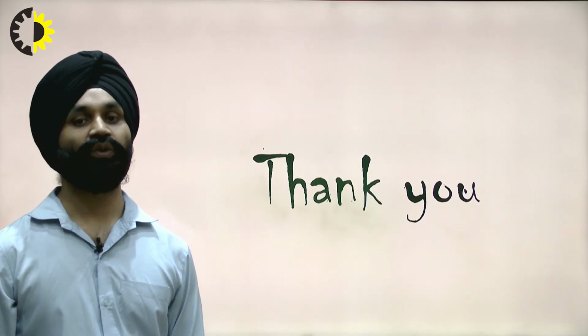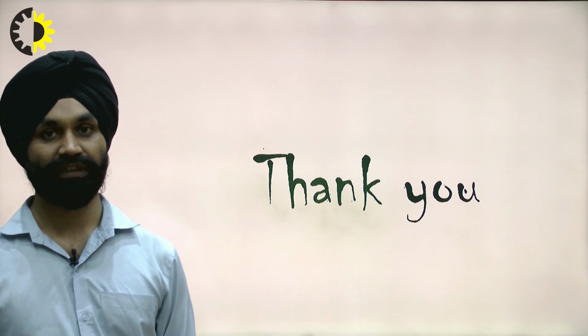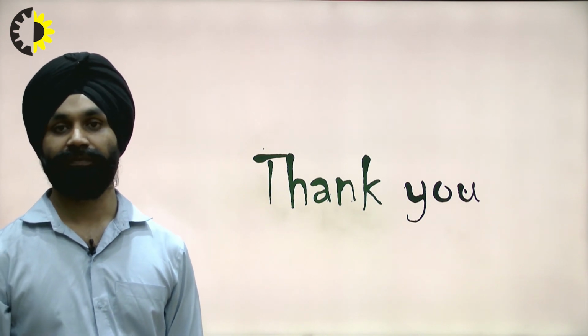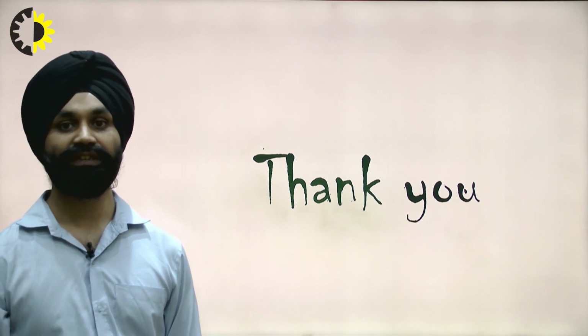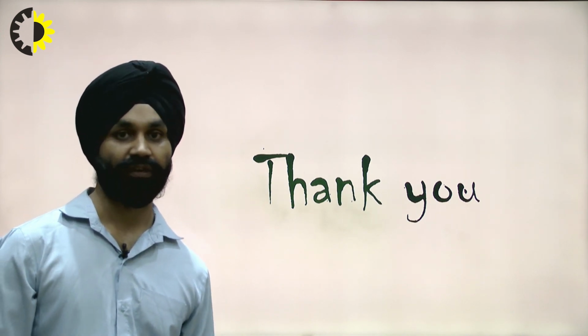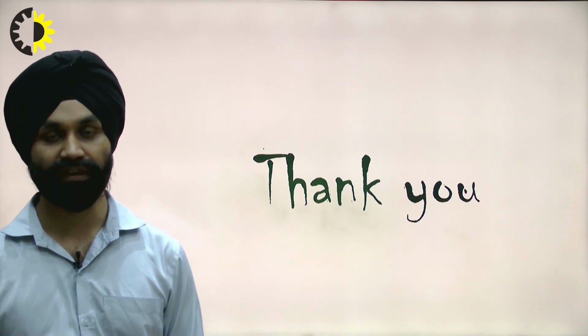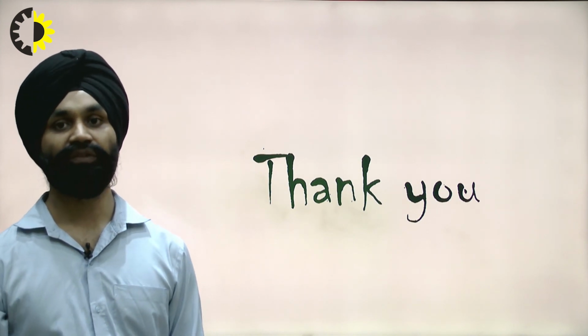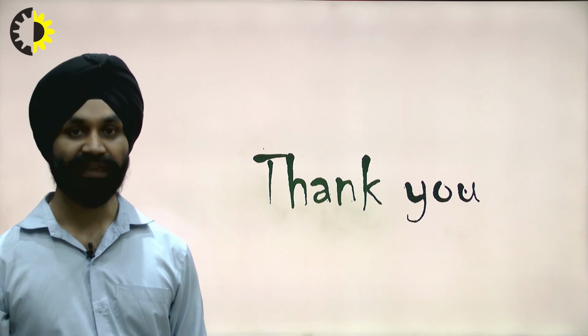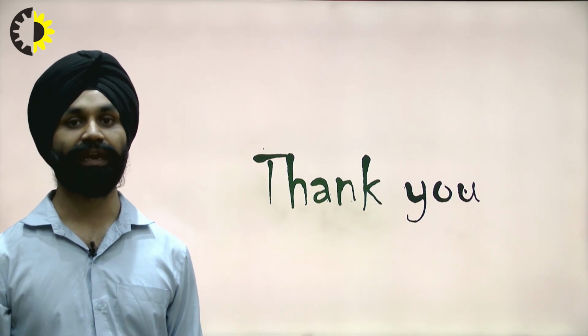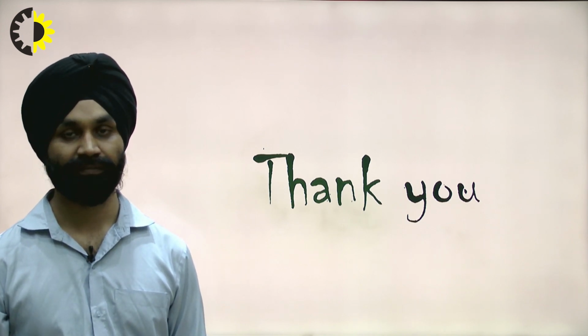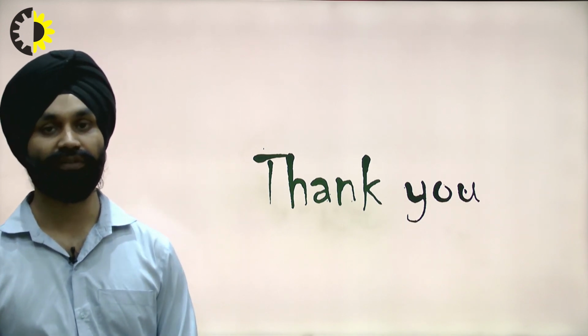Thank you. So in today's lecture, we have discussed the basics of the GIC. Then we discussed how, from a grounded inductor, we can create a floating inductor, and then the application of these inductors in active filter design, from the passive filter to the active filters.